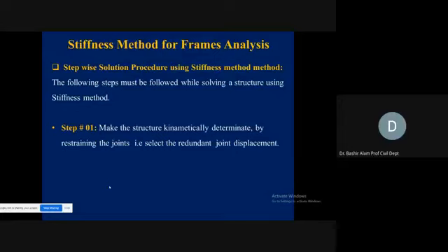Step number 2: we were constructing the ADL matrix. And what was the ADL matrix? Those were the fixed end actions corresponding to the unknown joint displacements in the restrained structure. So step number 2 was about the ADL matrix formation. What was step number 3 now? It was the construction of the stiffness coefficient matrix. And how do we make it?